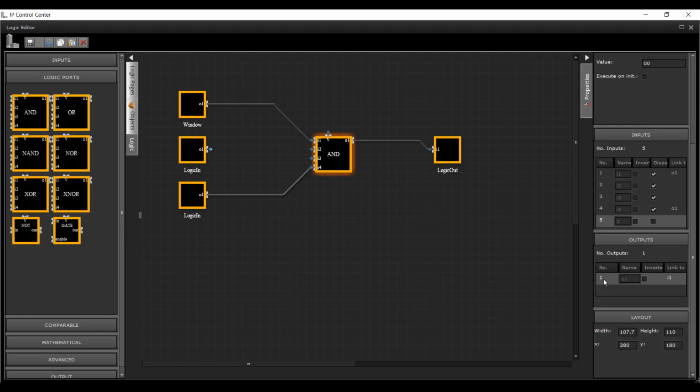If, for example, the output of a gate calculates the value -5, but the data point type connected to the output has the type unsigned, the value is limited to the value range of the data point. In this case, the value sent is not the calculated value -5, but the limited value 0.